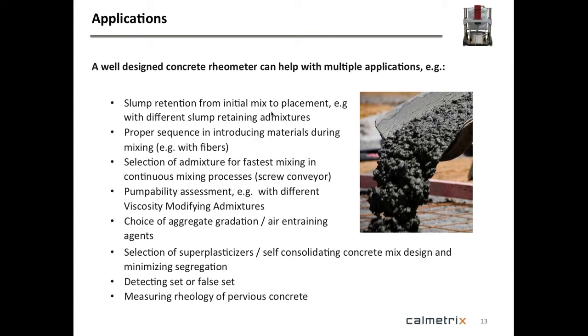You could look at choice of aggregate gradation, so having different particle size distribution of aggregates, coupled with different air entraining agents, will give you a very different rheology. And you could look at this again easily and continuously, because you mix your materials in that bowl, you put them directly in there, you don't have to have a separate mixer, you put them into the vessel of our rheometer, and then you start mixing and measure at the same time. Both aggregate gradation and air entrainment have a very, very large impact on rheology, on workability of concrete, and testing both together makes for a complex test matrix.